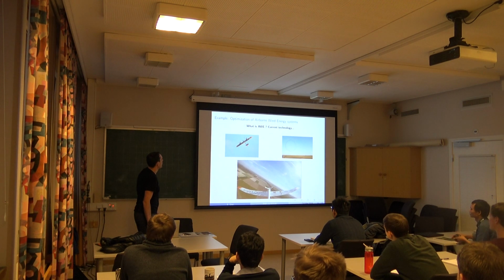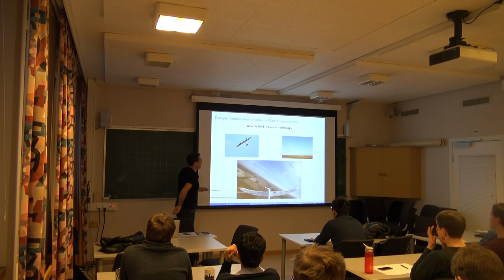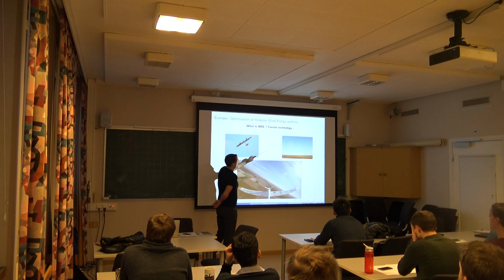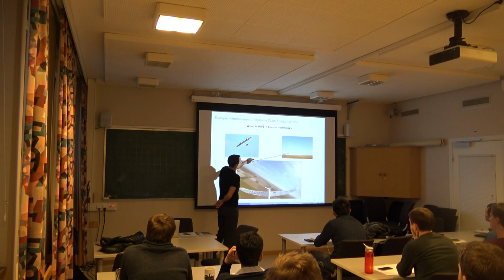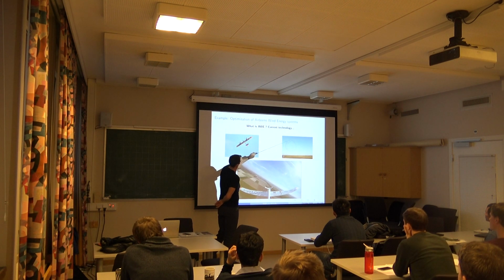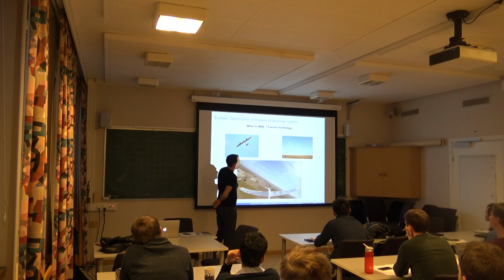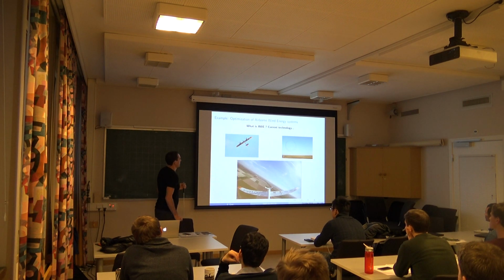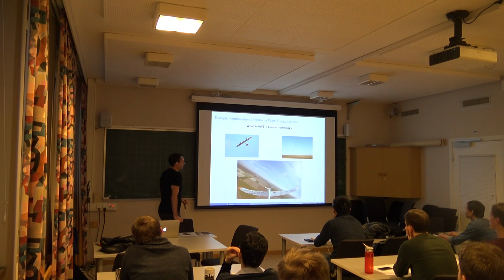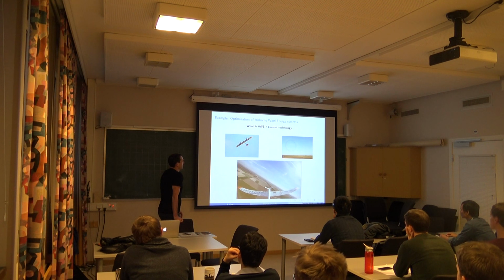Maybe it's gonna work. But the bottom line is that you have a periodic optimal control problem here. You want to maximize the energy that you harvest, or basically the average power that you harvest on this trajectory, and it has to be periodic. You want to come back where you started. And it's a fairly complex system, and you have a lot of physical effects that you need to trade off to maximize your power. So it's really not a system where you could easily guess the correct trajectory to fly.